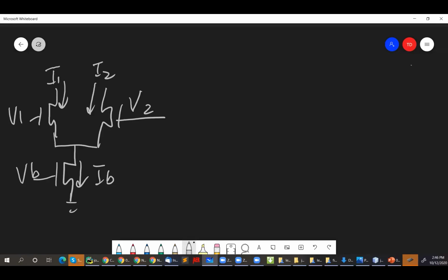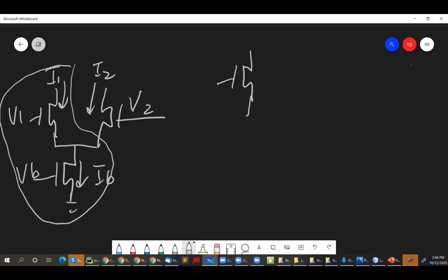Okay, and so the bias current here, if I look at just one of them, right? So we're going to do this. Yeah. So you recognize that? That's a source follower, right? Assuming that you tie this to VDD, because with a source follower, if we're talking about an NFET version of it, it's got a bias current here to set a fixed current flowing through the bottom. And then this is your output, and here's your input.